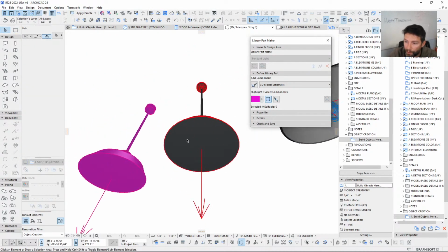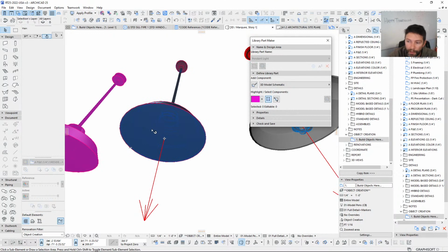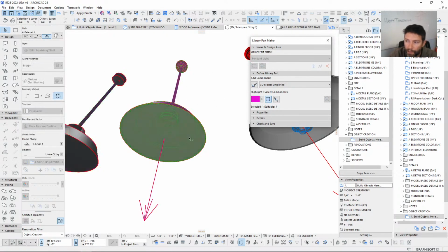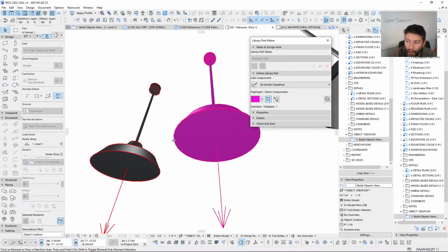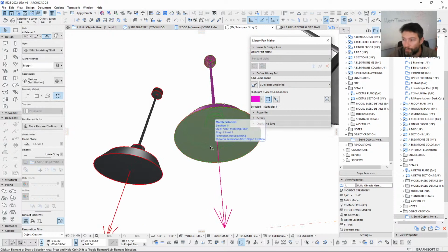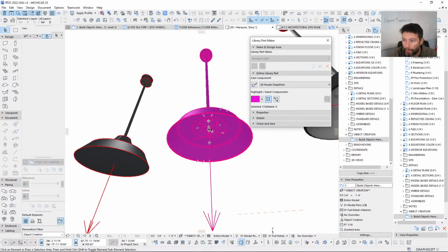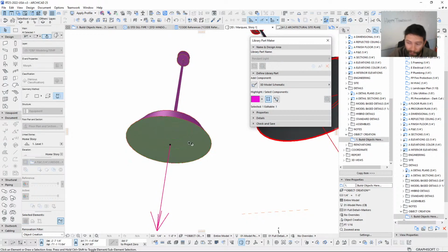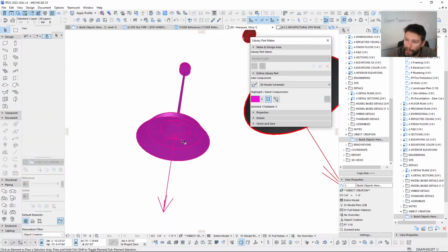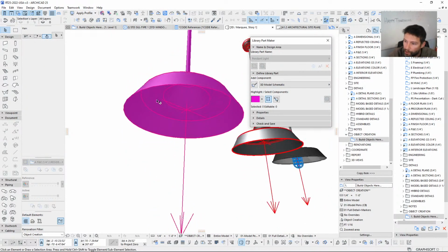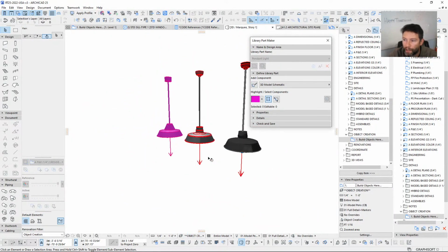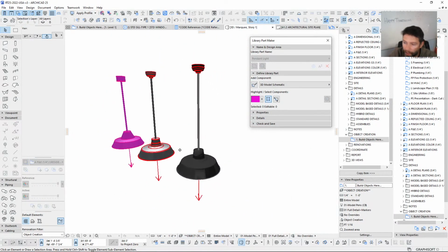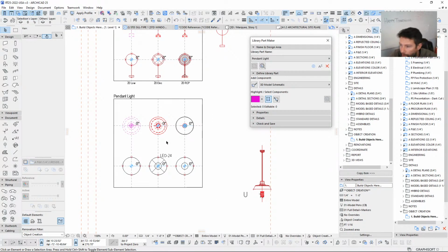There's a few other things that we need to do here. Because this is a morph that has a closed bottom, we definitely want to get rid of that bottom there by opening it up. So by hovering over this, I'm holding down Shift over this as we select. That way we can select that face, and then we can just simply delete that and open it up so that now we can make sure that that light source can shine out there. So, okay, there we go. We now have all of these set.